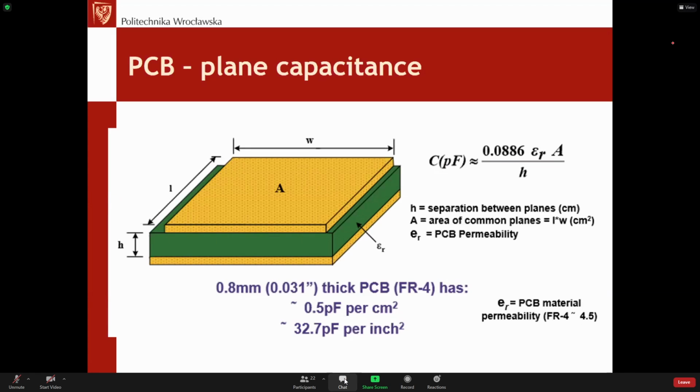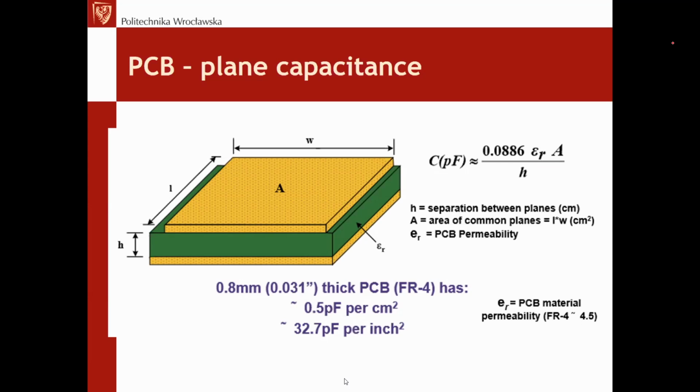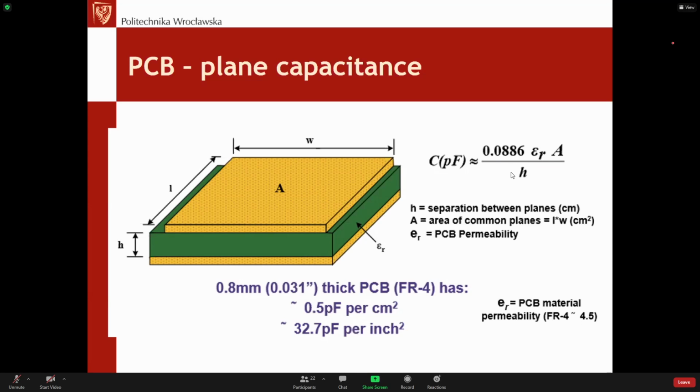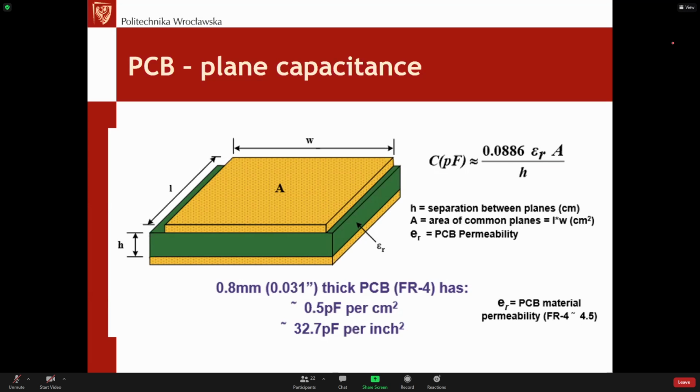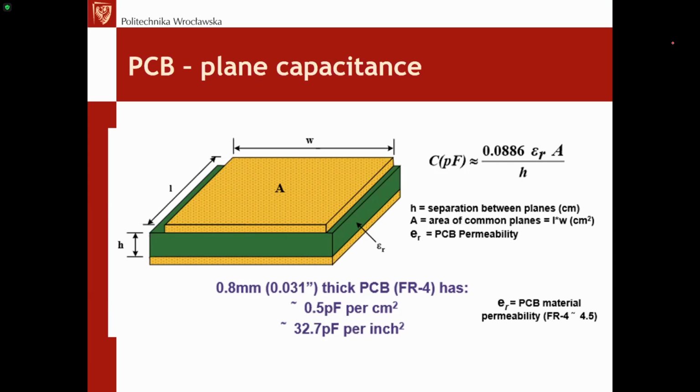Actually, in the case of high frequency signals, there is always a trade-off between the characteristic impedance, because that's what we care about, and the size of the high frequency track. Normally that's not such a problem.